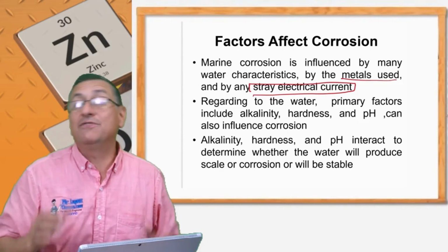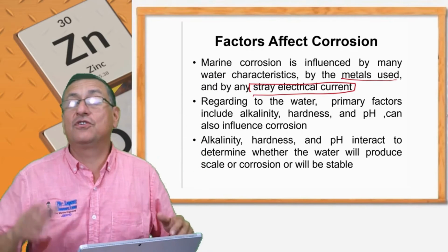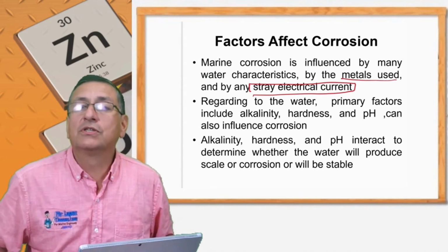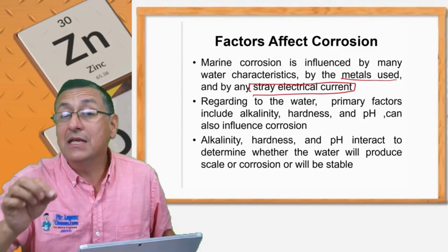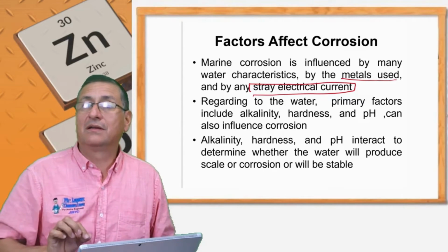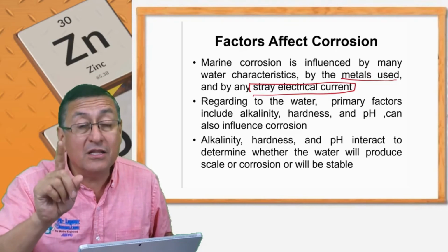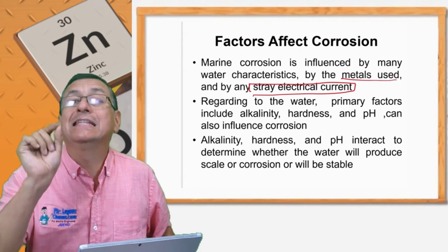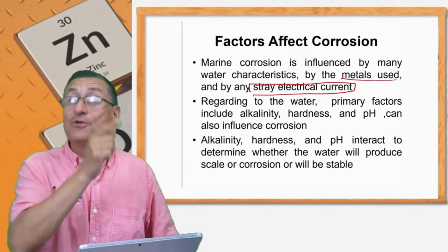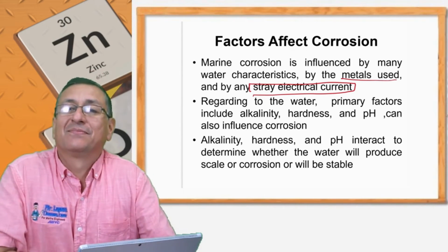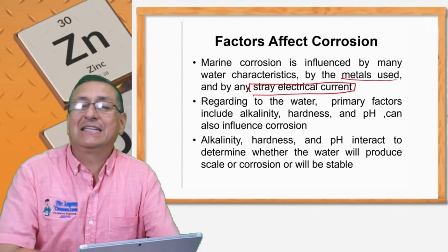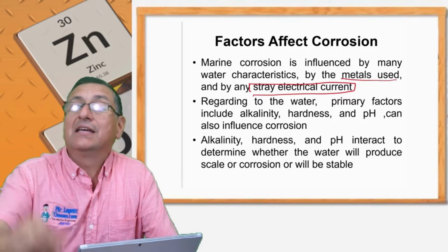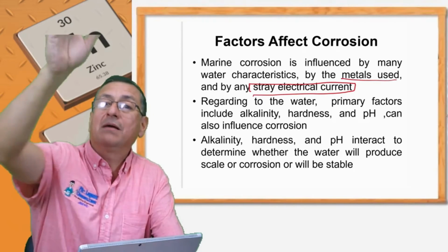For that reason, if you check the ABYC electrical static guide and other books, they say the grounding, the bonding cable, is a non-current conductor, but is used to drain small DC currents, those static currents. That static electricity is drained through the bonding into the grounding, into the sink, and bye-bye.